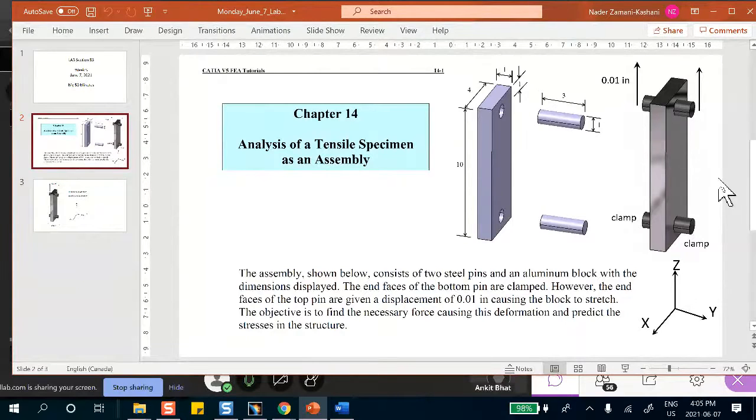If you're only pulling the top bar up, wait, when you say plane of symmetry, it's in terms of geometry, right? No, plane of symmetry means geometry plus the loading. That's what finite element means. It's not only geometry. In finite elements, all of these must result in symmetrical deformation. So it's not only geometry. The XY plane wouldn't be symmetric because of the deformation on the top. There's only deformation on the top half of the XY plane rather than the bottom half.